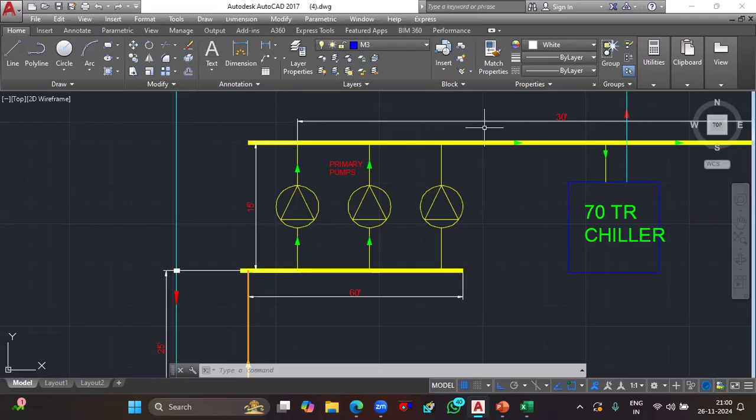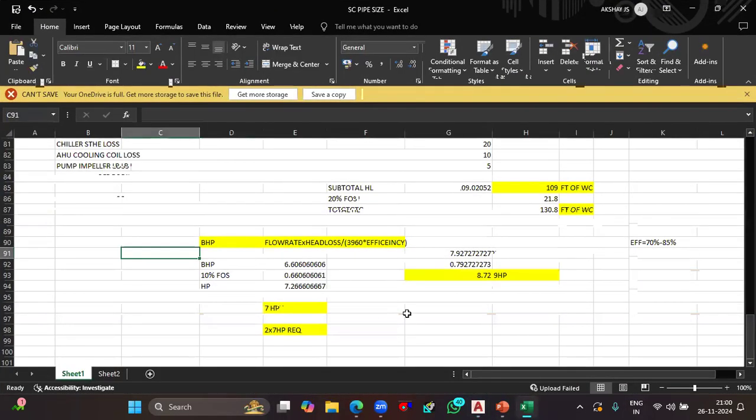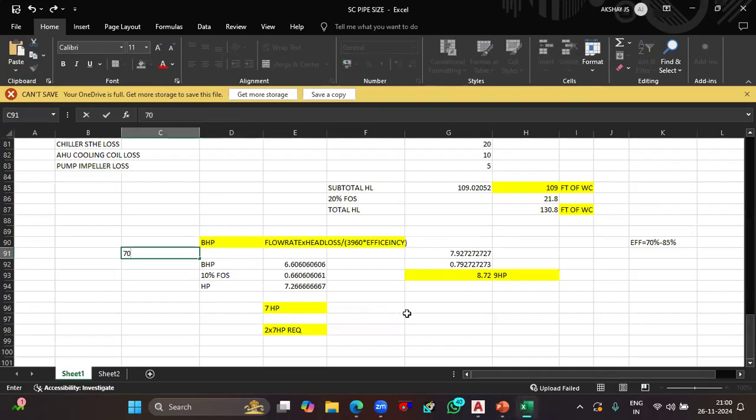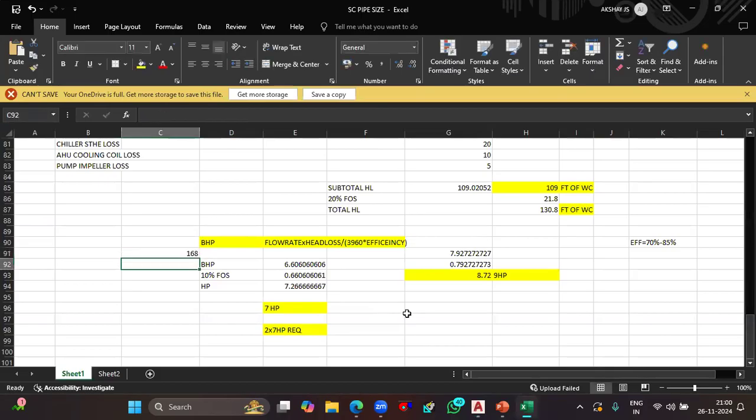That's it. So I hope you all got this point. For the head loss, where did this 168 GPM come from, where did we derive that from, sir? We studied that for a single pump it only carries 70 tons, isn't it? Single pump of 2.4 GPM per ton, that is 168 GPM, for a closed single piping pump system. Remember or did you forget?